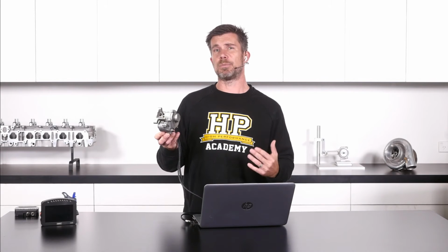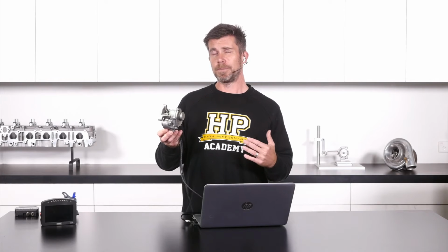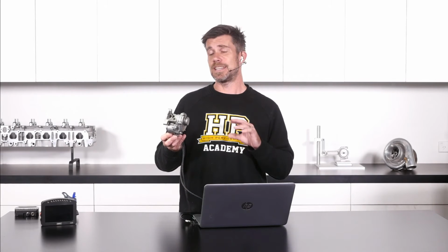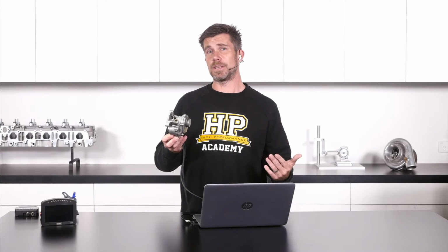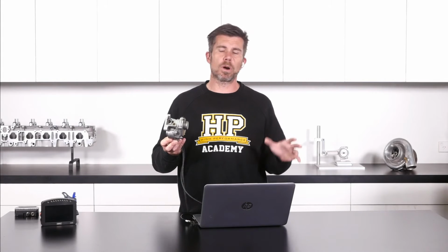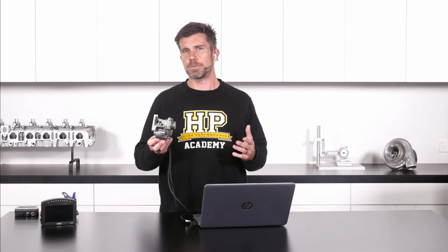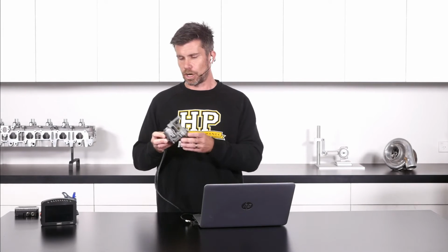For those who aren't aware, the oil metering pump is essentially a stepper motor drive that injects oil into the rotor housing. Most but not all competition rotary engines tend to do away with this and run premix instead, where the oil is actually mixed in with the fuel. There are pros and cons on both sides of this, but this is the way that we've decided to go.